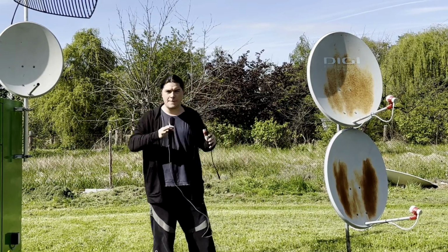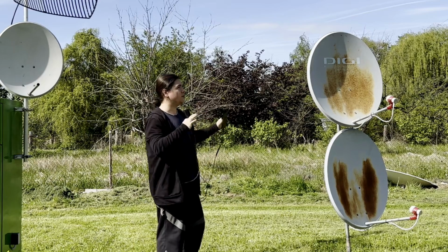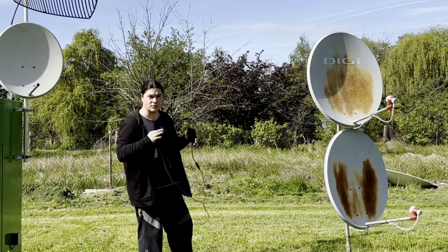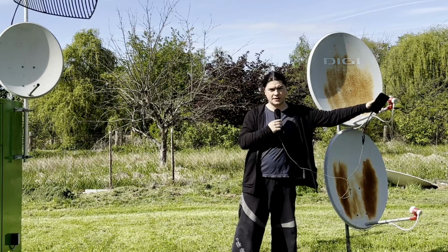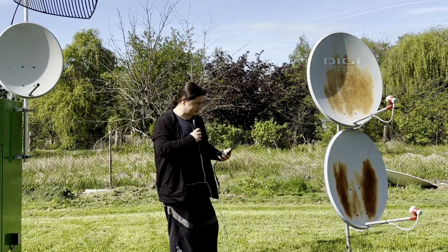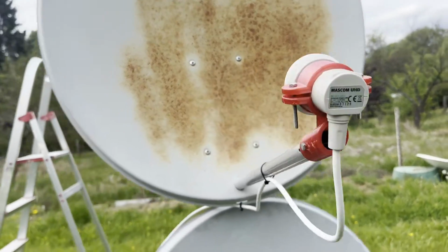So what all of that compounded means is that you can take whatever setup you have, or you can buy, or you can find for free. Usually you can just take the entire thing and reuse it for QO-100, although I would recommend buying a new PLL LNB, making sure it's at least somewhat stable. We are going to be taking a look at that in this video in more detail. I recorded a section with a practical demonstration of how you can receive this satellite.